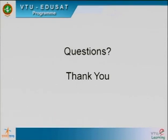In today's class we have finished the 8255. How is it different from your latches and buffer? We have programmable ports here, the control word for 8255, the address decoders for 8255, later the in and out programming in Visual C++ and Linux C++, that is for Windows and Linux versions. What are the changes in the IO instructions? So this concludes module 3 of your syllabus.